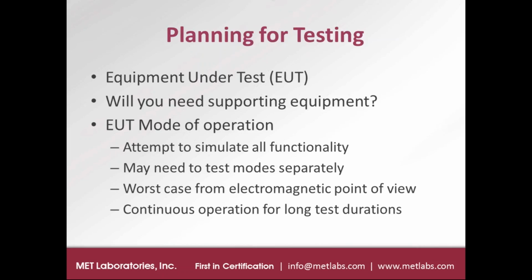The other aspect of EUT modes of operation for EMC testing should be continuous operation for long durations. If your EUT in its mission only operates for 30 milliseconds when you push the button and then stops, it's not going to accommodate EMC testing. So you may have to come up with a special test script or even test firmware that causes the EUT to operate continuously during EMC testing.